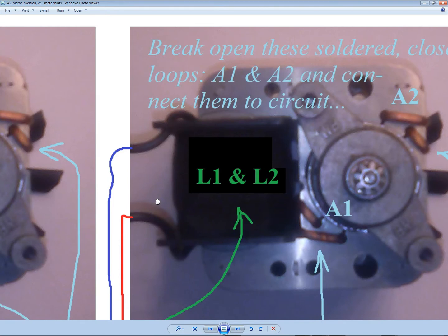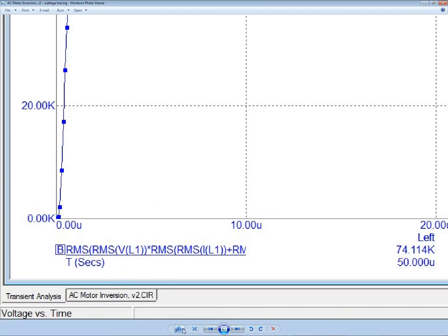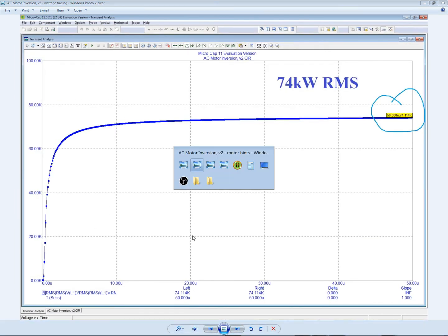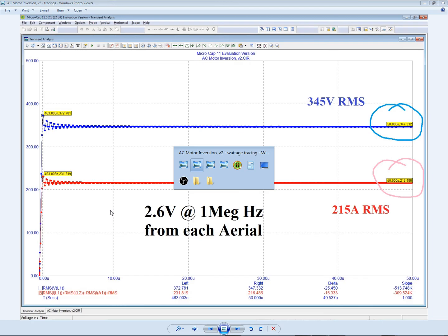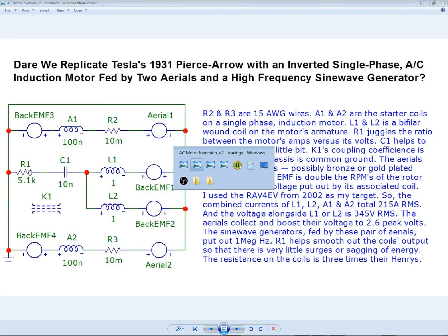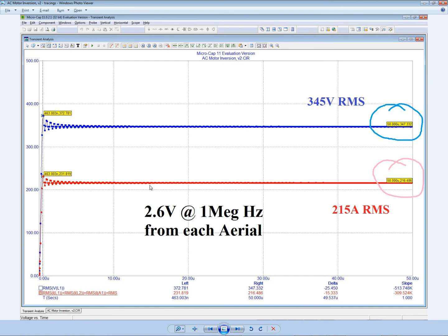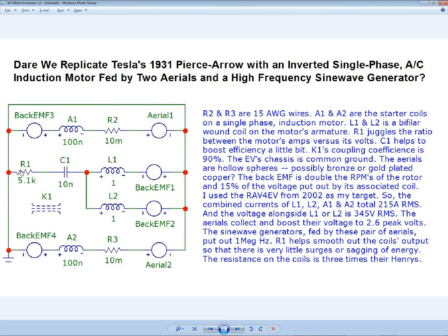And this was a problem I was having. When I had no resistor there, when I took this resistor out, the RMS values tended to wobble all over the place and take forever to try to even out. In fact, they wouldn't. The voltage kept dropping, and I couldn't afford the amount of time that I was spending waiting for the simulator to finish its calculations so that I could make it give me some tracings. It was remarkably inconvenient when this R1 resistor I had taken out wasn't here.